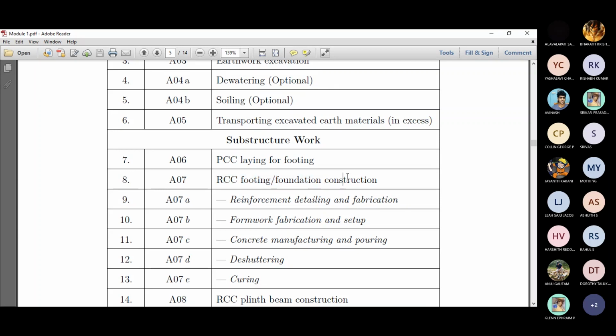Right. So once that is done, then we will be removing the formwork, which is called de-shuttering. There's a definite period for de-shuttering for different elements, like foundation has different days, and beams, columns, and slabs have different days. And generally for slabs, you might have seen at construction sites, they don't remove the formwork even though it can be removed in 7 days to 14 days.